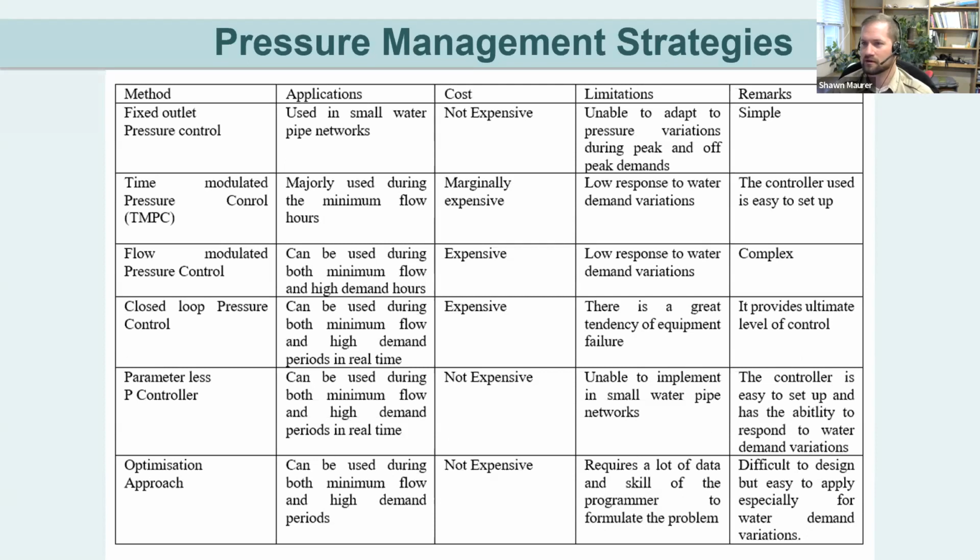Say, maybe you've got a stadium and a bunch of people come in for an event. There's an increased water demand there on your network. Special events like that, it's not going to react to. It's going to react mainly to that programmed regular pattern that happens. So it's a little bit more expensive to implement. It gives you a little bit better control, but it's not going to react dynamically to your system. It's going to react based on what your pre-programmed time settings are.